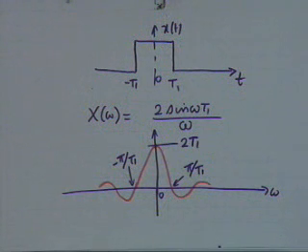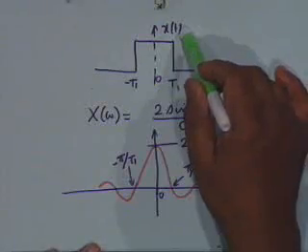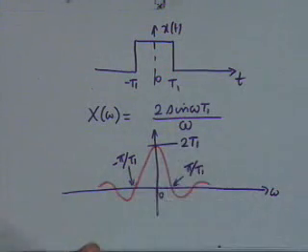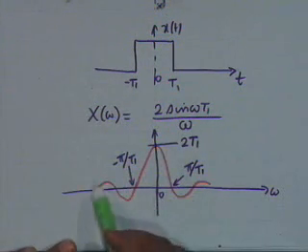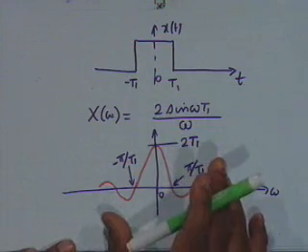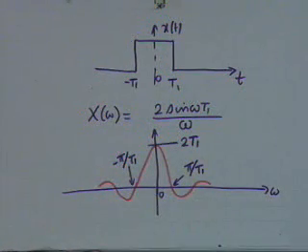Now the question that I ask is the following. Exactly like Fourier series, which contains an infinite number of terms, k equal to minus infinity to plus infinity for a periodic function, if I wish to reconstruct x of t from the spectrum, obviously I have to take the infinite spectrum from minus infinity to plus infinity. In the case of Fourier series, it was a line spectrum. In this case, it is a continuous spectrum. I have to take the spectrum and take its inverse Fourier transform.